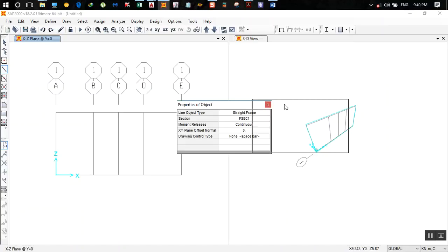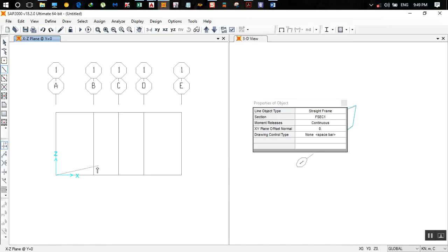After that we draw a truss like this, like this, like this, and this. Now you're stuck here. All you have to do is click on the right mouse button, and you can again begin. There is yet another option, Quick Draw Frame Cable.